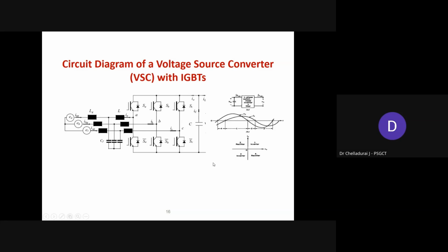Or simply, if you want to convert DC into AC, and the inverter pole voltages, ABC voltage magnitude, is more than that of grid voltage, then power will flow from DC to AC. In quadrant 2, the voltage and current, one is positive, another one negative, so the power is reversed.